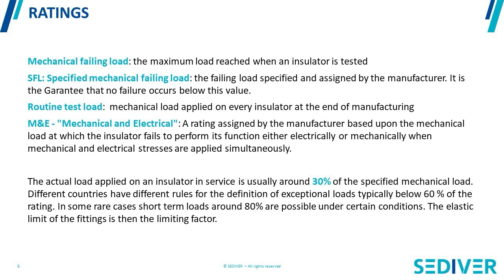There is another load called the routine test load. Every insulator, I really mean it, every insulator, 100% of everything that is produced goes through a routine test load. This is a mechanical load that is applied on every insulator at the end of manufacturing to be sure that manufacturing is okay.